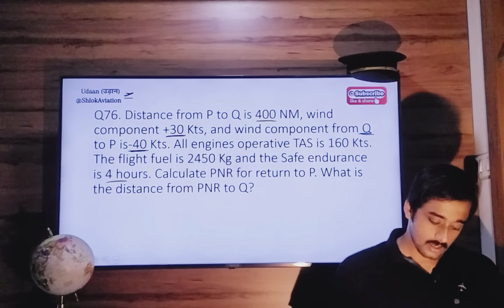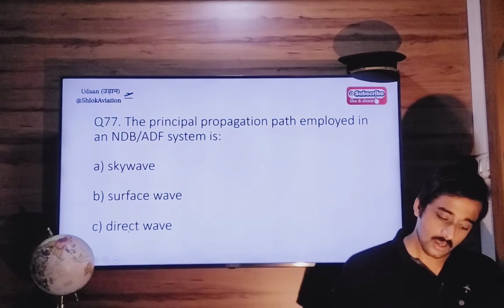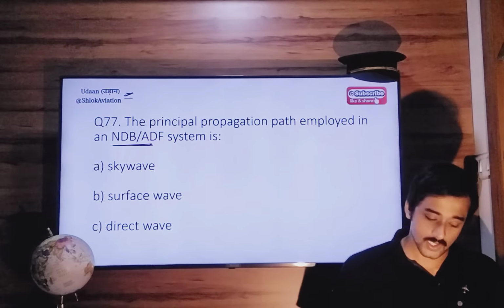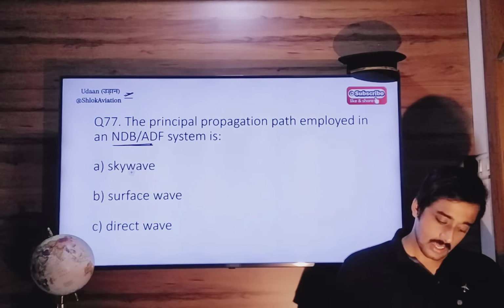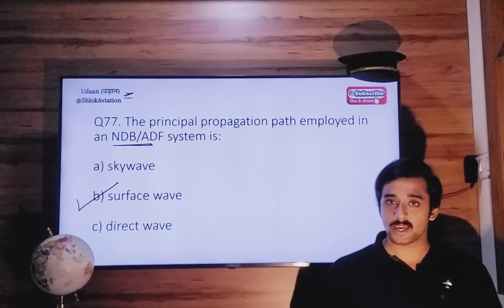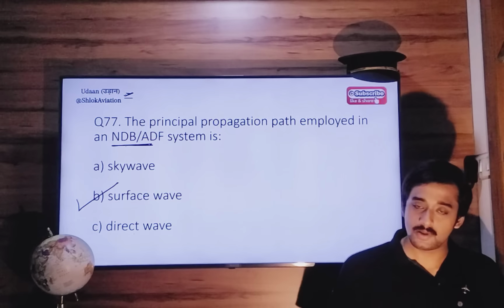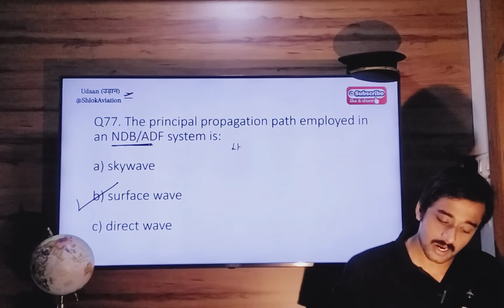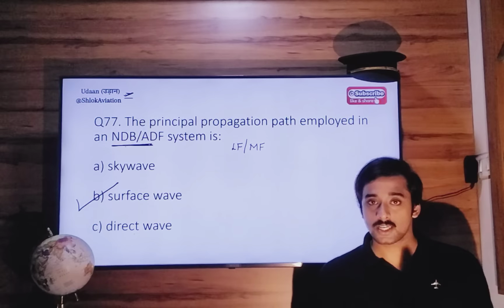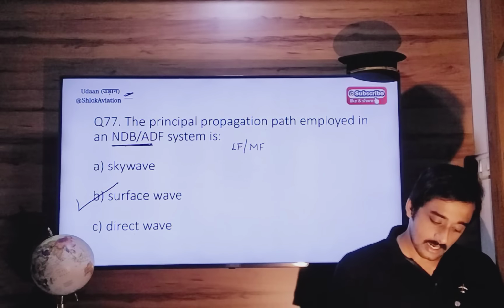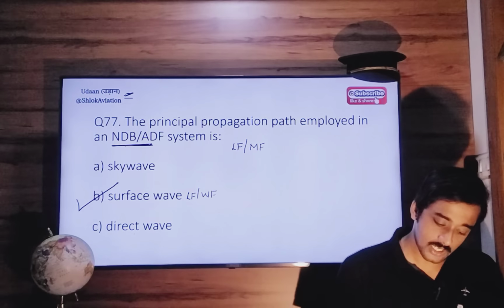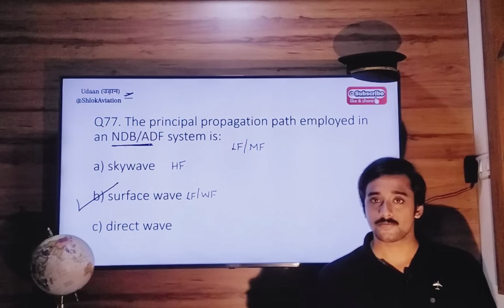Correct? Next question. The principal propagation path employed in NDB ADF system is: skywave propagation, surface wave, or direct wave. So the correct answer is surface wave propagation. NDB works in the frequency band of low frequency and medium frequency, and all radio propagation happening in this frequency band is surface wave propagation. Skywave propagation happens in the high frequency band. Next.